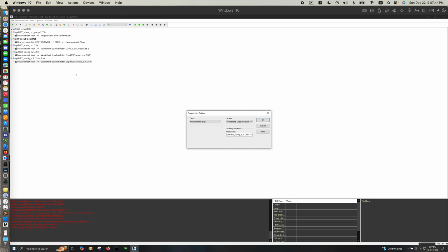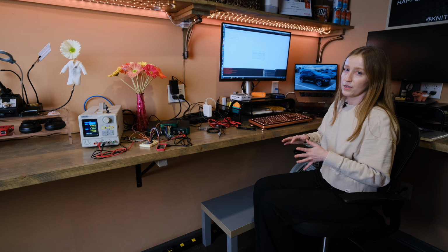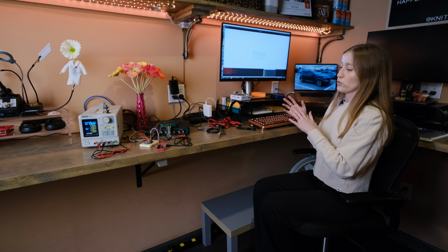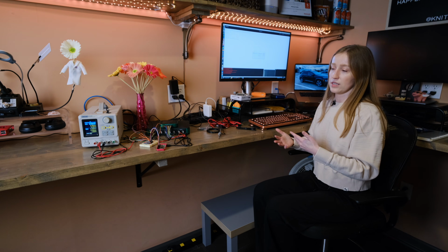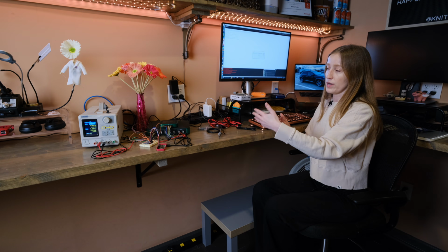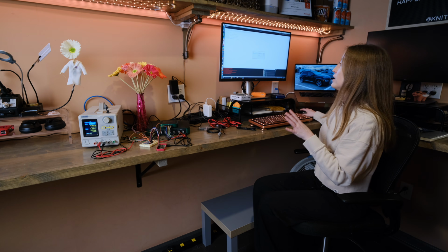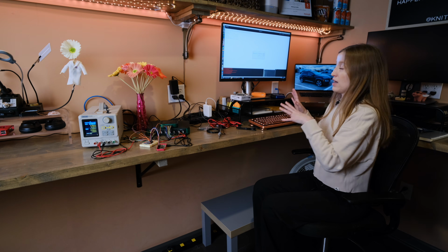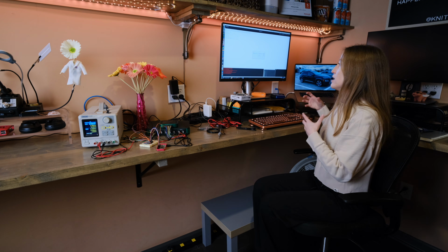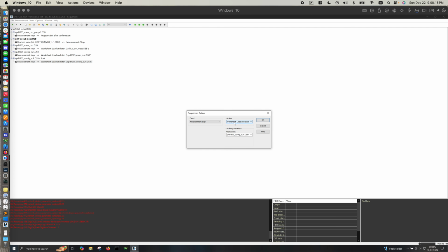Just to show what I have here, the event is measurement stop. Because I have this worksheet configured to automatically stop when it queries the voltage setting back, if it reads back 5 volts like it should, the worksheet stops itself. That event, measurement stop, the event of the worksheet stopping itself, is the event that triggers the action to load and start the next worksheet.